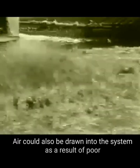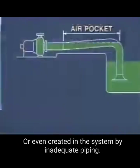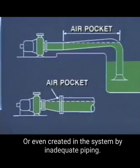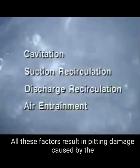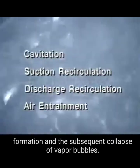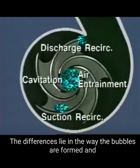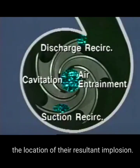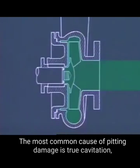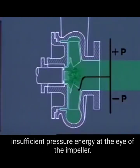Air could also be drawn into the system as a result of poor suction tank design, or even created in the system by inadequate piping. All these factors result in pitting damage caused by the formation and the subsequent collapse of vapor bubbles. The differences lie in the way the bubbles are formed and the location of their resultant implosion. The most common cause of pitting damage is true cavitation, which takes place when the vapor bubbles are created by insufficient pressure energy at the eye of the impeller.